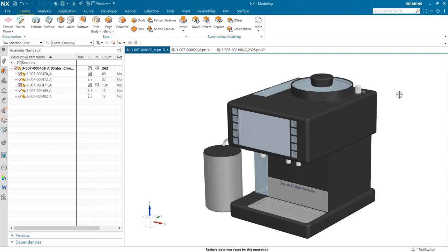I'm going to be discussing a few enhancements to the PMI region command and how these improvements can improve your workflows. The three primary improvements to PMI region are an updated user interface, enhanced to emphasize required inputs, the ability to select non-planar curves for arbitrary region boundaries, and improved crosshatch for surface-conforming regions.